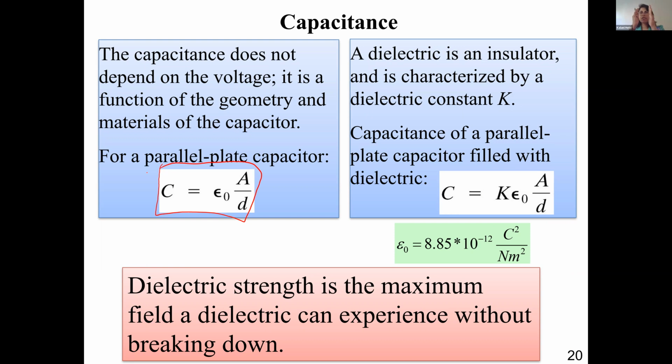The other parameter is the distance between these two plates. If the distance is greater, then your capacitance will be smaller. When the cross-sectional area is greater, your capacitance is going to increase. When the distance decreases, the capacitance will increase too. And epsilon naught, which I have in there, we call the permittivity of the material in between these two plates. That is the epsilon naught value that we can use as a constant in here.